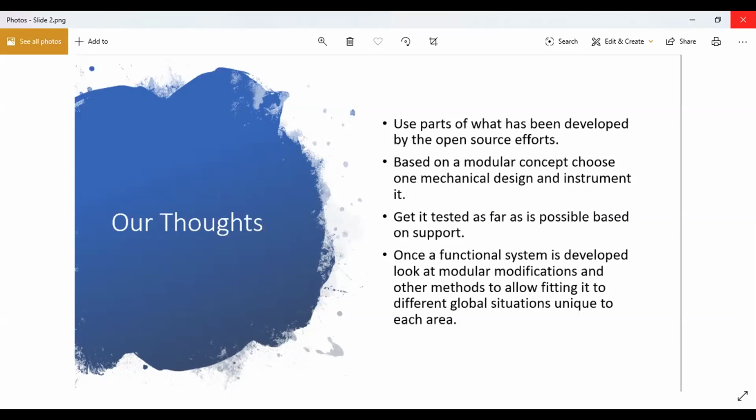Basically, when you push the air into the patient, it has to go through one path. And then when the patient exhales, it needs to go, literally, not back through your machine, but through a separate valve. There's a special valve for that: when you're under the positive inspiratory pressure, it actually shuts the valve. And when the machine is actually, I like the piston design, by the way.